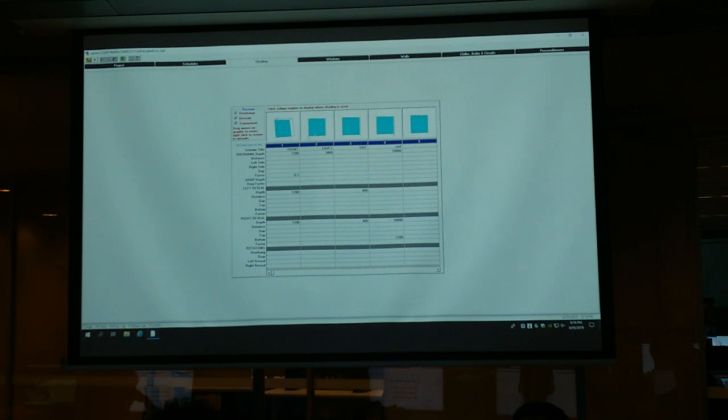Okay, and just try the numbers, and then you can see the change of the location. And windows, you will need to give a name as well, because later on the wall, the wall side, you will input the name of the window, and also overhang, whatever review, and then we will automatically locate it.